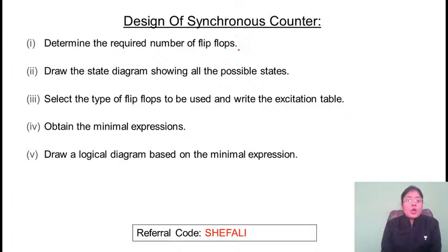So first of all, whenever you design a counter, you need to determine how many flip-flops are required. How will you determine how many flip-flops are required? For example, if I want to design a counter to count 5 states, then how many flip-flops will you be taking?